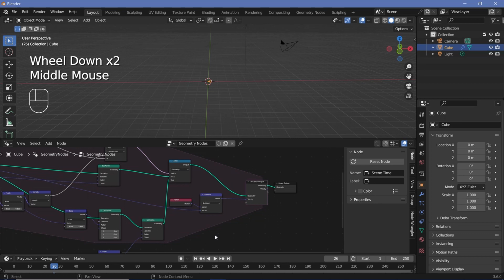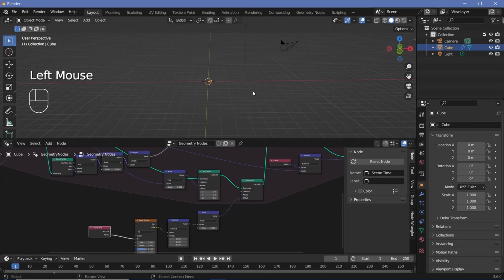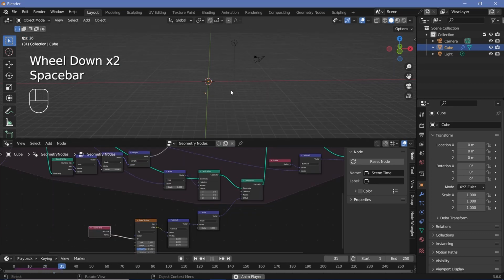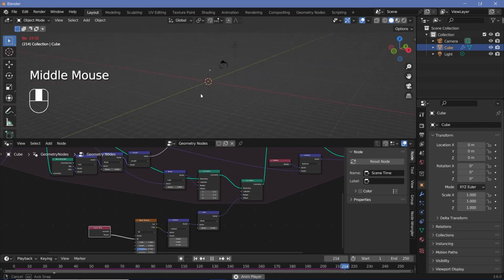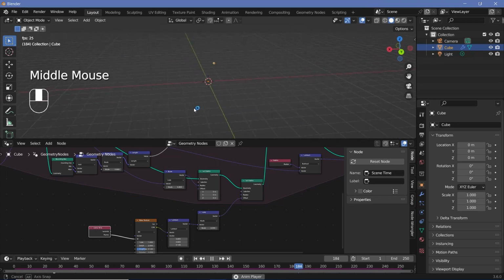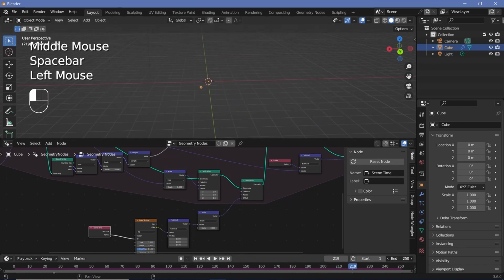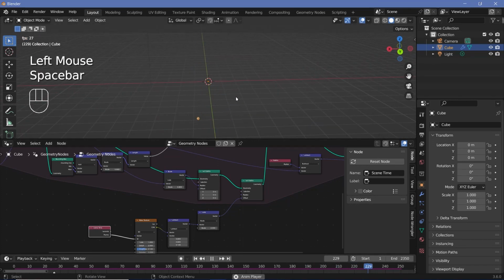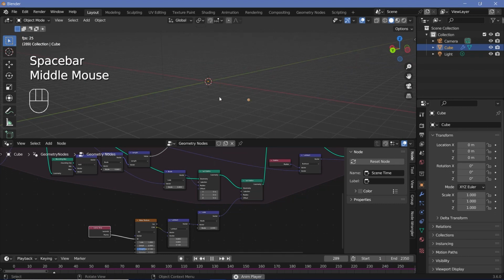So with all of those changes, let's go back to frame 1 to reset the simulation and play the simulation. Now you should be able to see the sphere bouncing around in random directions, and it's always going to stay within those 5 meters. Now it's actually moving in 3D, so it's fairly hard to tell, but it is moving in random directions and it is staying within the sphere. So we can increase the end time to something really large so that it continues for even longer. But yeah, you can see how it's moving around in random directions and staying within the sphere.